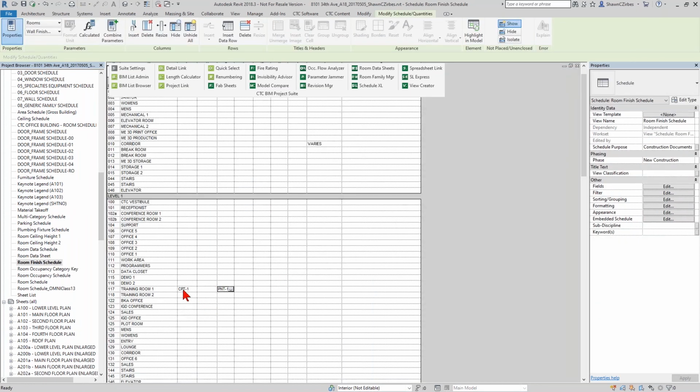disillusioned like I did. Now I expect this to work a lot like Excel, looking like a spreadsheet. But if you highlight a couple of values here and you Control C, arrow down, Control V, you cannot copy paste things. Yeah, I know, room schedule keys, you could build those up, but then you got to teach interior designers how to use a different schedule to set a room schedule key up and then assign it to rooms. And then if they want to make an off room that's not a part of the schedule key set, they remove a key, lose all their data values, enter it all back in again.